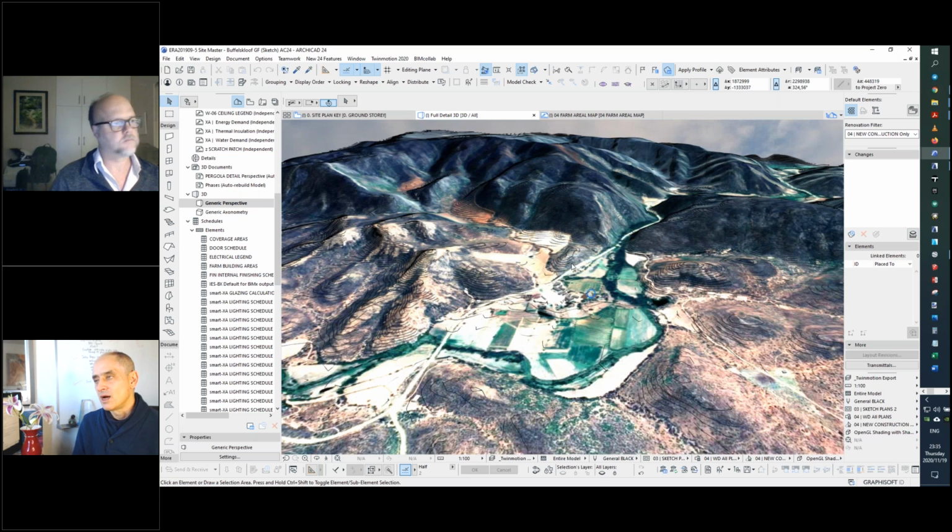I think we've certainly seen the context of all these buildings and some of the interesting architectural information there. One other thing you mentioned to me was that glass box ceiling, that you've got some natural cooling. Instead of using high energy air conditioning, you're using misting and evaporative cooling strategies, which can keep it cool even with the doors closed, though it's really hot outside. Yeah, that is correct. Even opening the doors strategically will create a draft, and by means of the misting system and the draft, you create a cooling effect in the space.